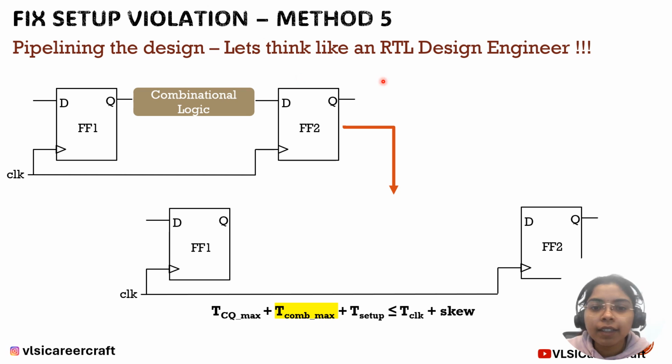Now let's again think like an RTL design engineer. Here we are trying to change the architecture which is used traditionally, like launch flop, capture flop and combinational logic. Now the combinational logic is having 4 picosecond delay, let's say, which is too high to satisfy this equation.